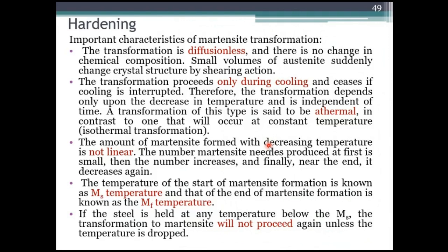Usually this transformation proceeds only during the cooling operation. After heating, only as the cooling takes place does the transformation from one particular structure to another occur; it depends only on the decrease of temperature. It cannot happen at a constant temperature, because constant temperature would make it an isothermal transformation.